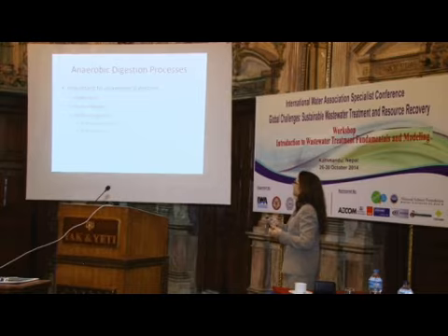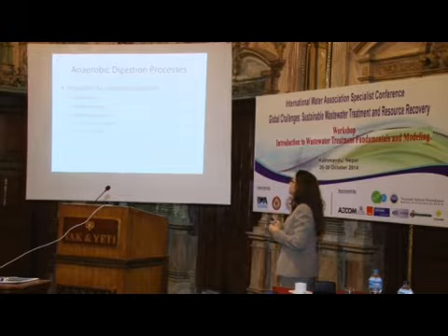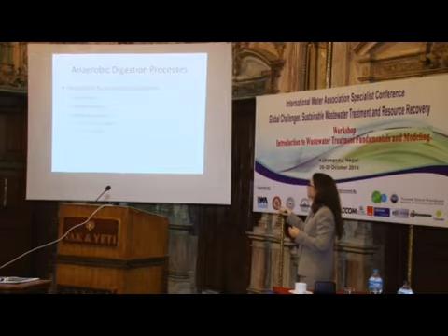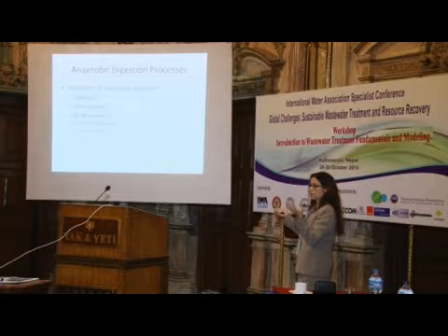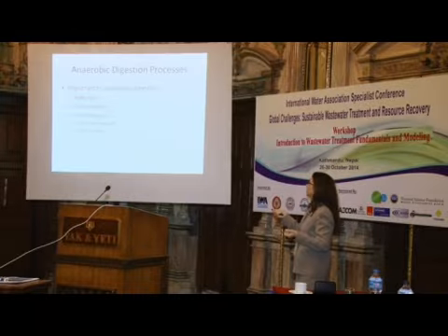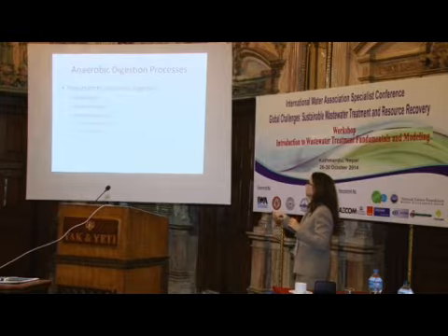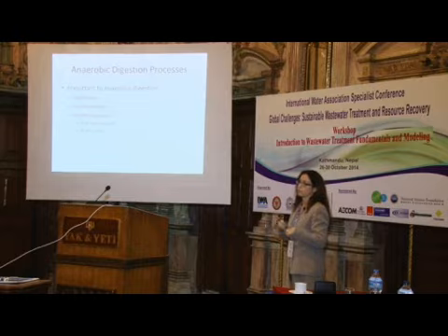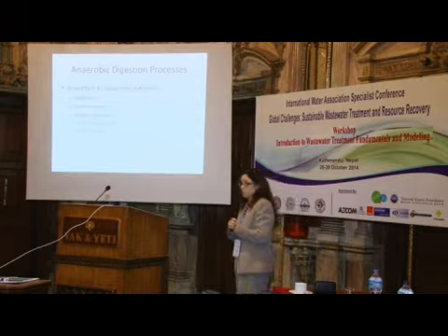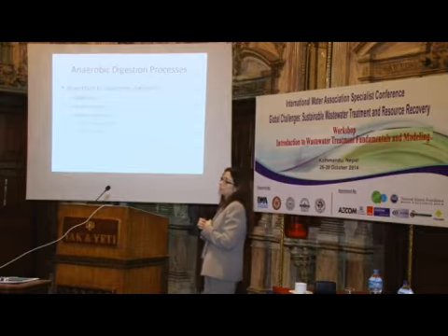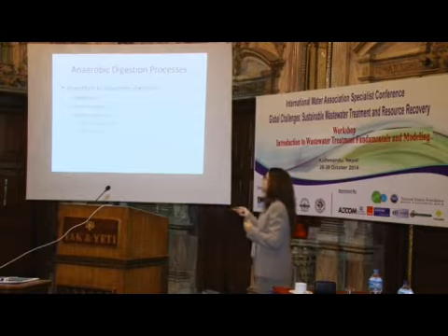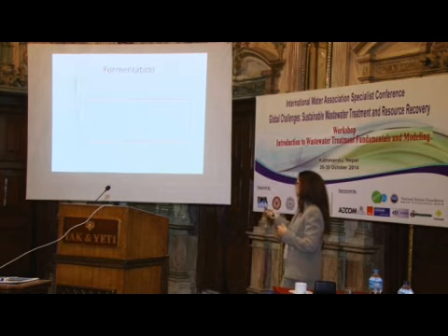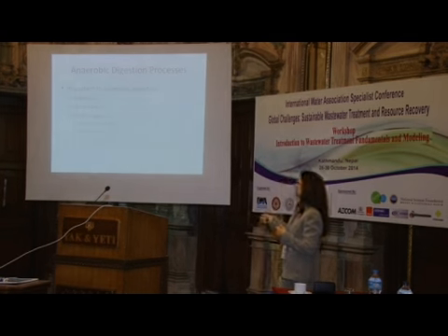So again, in anaerobic digestion, our critical processes are the hydrolysis, because we have these large molecules to break up. Once they're broken up, fermentation, methanogenesis, and then we have 2 different kinds of methanogenesis. We have hydrogenotrophic and we have acetoclastic. So what I'll do is I'll go through each of these in some detail now.